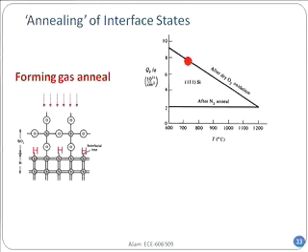And this is something you should understand, because people often ask you this in various interviews: why is silicon used on the 100 surface, although in many cases the 111 surface might have better mobility? The reason is that when you cut the 100 surface, the number of bonds per centimeter squared is actually less, and therefore the number of dangling bonds is less. As a result you have fewer traps on the 100 surface, and therefore people prefer it.